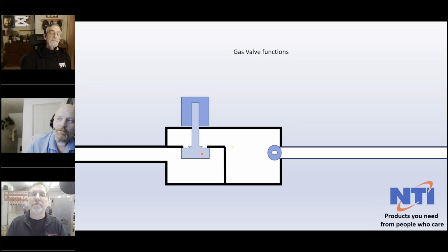So we've got another gas valve here. For anybody in the previous section, I'd asked you, how does gas pressure affect the flow through this gas valve? And one of the problems with a gas valve that's set up directly like this, where the gas coming in pushes past a restriction and then out to the gas line, is the higher the incoming gas pressure, the higher the outgoing gas pressure. So incoming pressure is directly correlated. Obviously, you can imagine a scenario where we are at 48 inches, that's going to really overfire your boiler quite a bit. One strategy people have tried in the past is to put an orifice in.